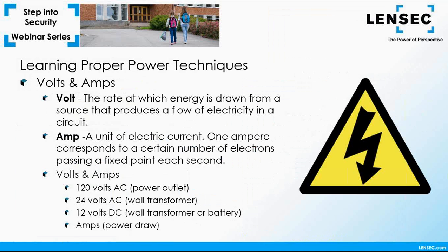Certain things come into play in determining your voltage drops: the power draw of the equipment, the length of the cable run, and the gauge of the power cable. It's best to find an online voltage calculator to determine voltage drop for longer power runs. If your voltage drops below the recommended level of the attached equipment, it can be damaged over time.